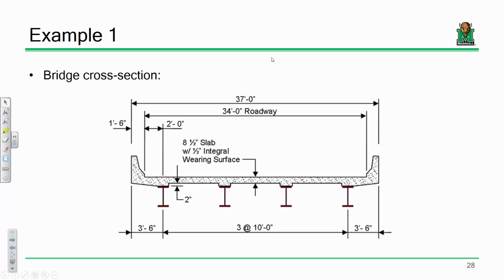When we look at our section properties, like our composite section properties, and we'll draw this on the screen so everybody sees it, we typically just say, our section looks like this. Now, there are some jurisdictions that actually do count on that little bit of concrete right there, like when they're computing moments of inertia. I don't think you can really count on it. So that's just me.